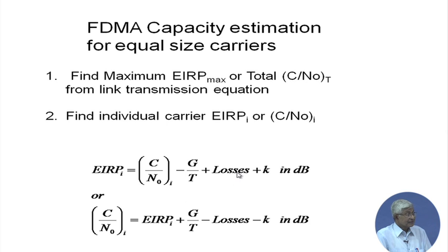It is the losses. As I told you, there are possibilities that if the filters are not designed properly, or because of any intermodulation or interference, some of the power will come into the wanted band, and therefore it will increase the noise, and that is where the losses will increase. So our intention is to improve the efficiency, to reduce those interference losses or spurious losses which are coming in.